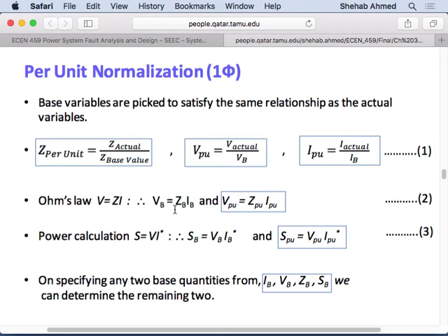If I have another transformer that is 1000 volts in the system, then 1000 volts divided by the 1000 volt base is 1 per unit. So this transformer is healthy, and that transformer is also healthy. But the per unit value here is 0.1 and here it is 1. Does it make sense? No. So it was not a good choice of base. It's useless, in this case.